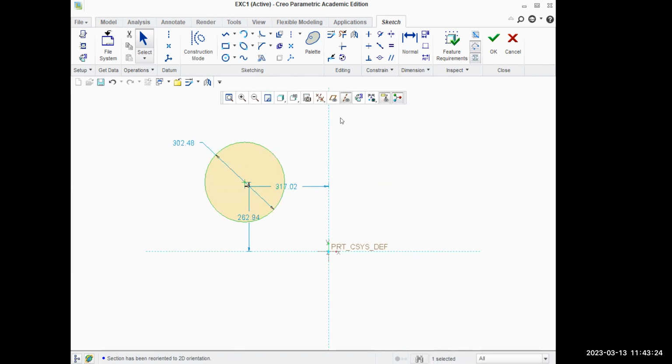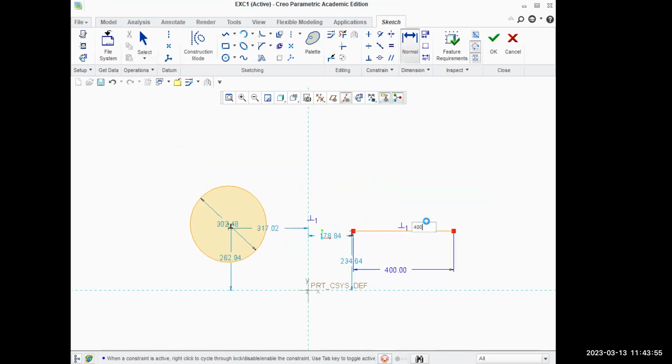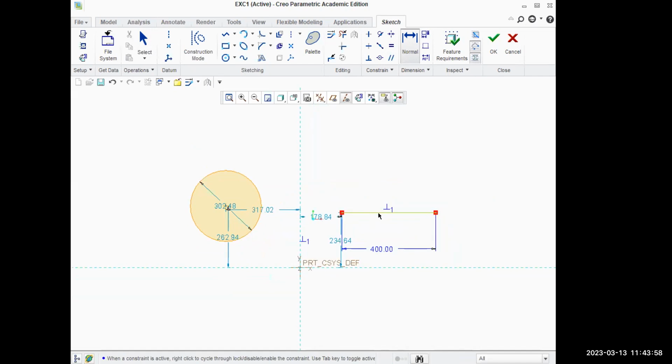Now you can see in Creo, if you drop entities, for example two entities here, and I didn't give any dimensions, the system itself will generate the dimensions. These dimensions are called weak dimensions. We are interested in converting them as per our requirement, which means user-defined dimensions are required. That is called strong dimensioning. If you pick and drop the dimension and then enter a value, this action fulfills that you have made the dimensions strong.